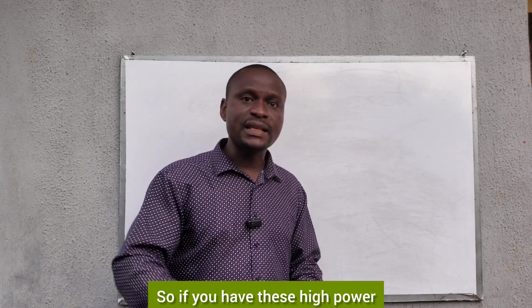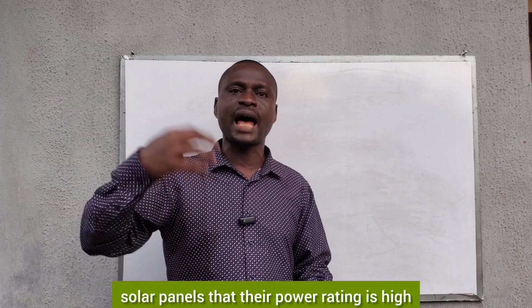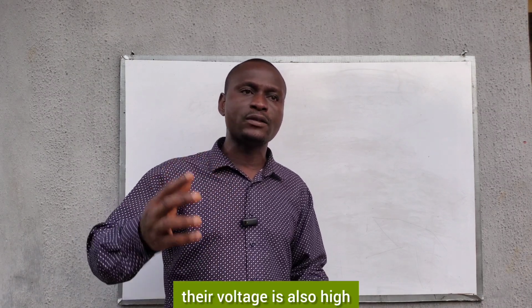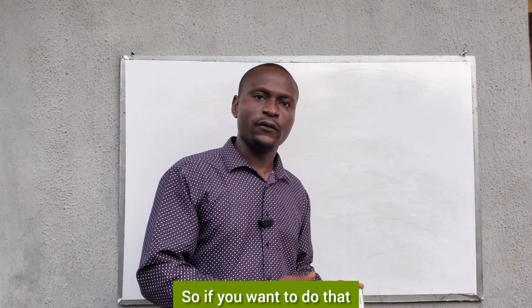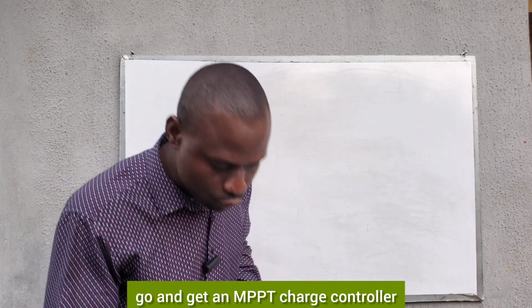So if you have these high power solar panels, you should know that most of them have a high voltage too. Using them to charge small low voltage battery banks is not too efficient. So if you want to do that, go and get an MPPT charge controller.